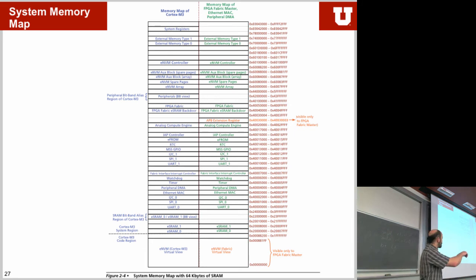Down here, starting at 0, is the non-volatile memory. That's where we want our code to sit. So this is where we will have code in it. That's where we load the PC, the program counter, from, where it goes and loads and starts executing the instructions accordingly. Right? It's also where we can have constants stored. If you have big tables of constants, for example for a sine wave, you store it in the non-volatile memory, not in your RAM, and then you read it out from the non-volatile memory most of the time.